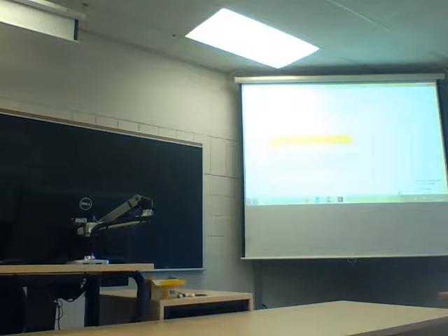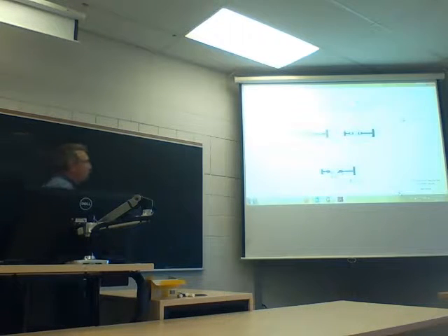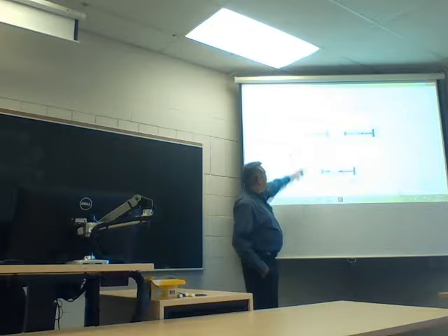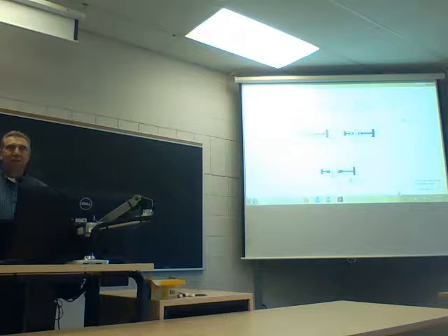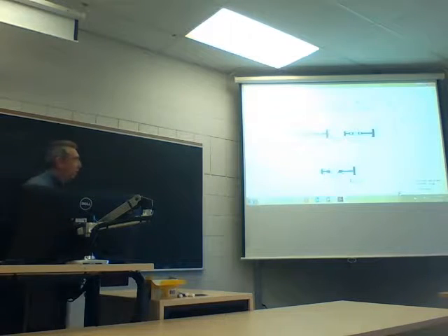Free piston compressors. They're special compressors. It even tells you: special cycle reciprocating compression, essential combustion chamber, usually diesel fuel. Pretty interesting thing if we take a look at the picture, then we can talk you through it a little better. So we basically have two pistons. This one here at the end is basically a cushion tank. You know what a cushion tank is? It's in a hot water heating system or anything. This is to absorb the expansion of the pressure. That's basically what this does as well.